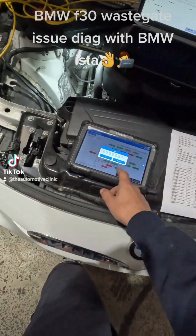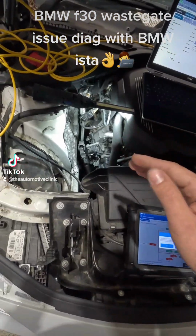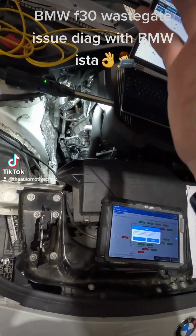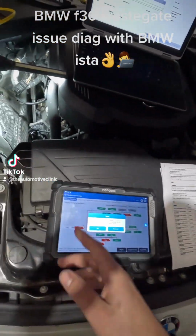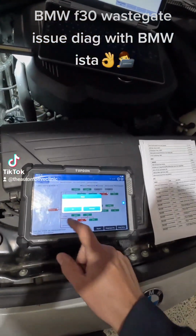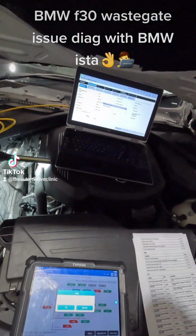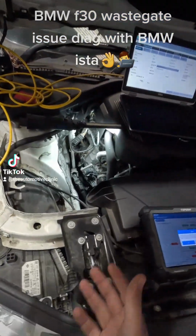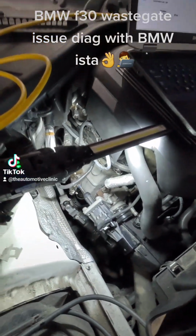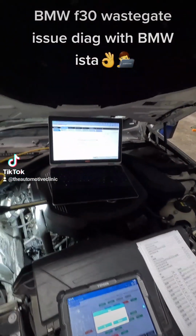Now when we attempt the wastegate adaptions with the aftermarket tool, it does attempt the adaption, so we can see it moves the rod in and out to the end stops, but it does not actually complete. It fails. So whether we've got a misadjustment here or a faulty actuator, that's what we're going to try and determine. From here, moving away from the aftermarket scan tool straight to dealer software, because we'll be able to calculate a test plan and get our measurements and see what's going on. So once ISTA boots up and reads all the vehicle data out, we'll get the ball rolling from there and see where we go.